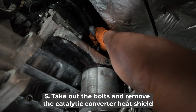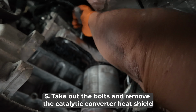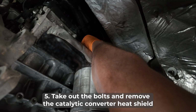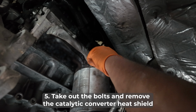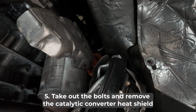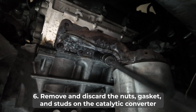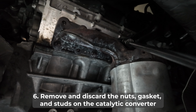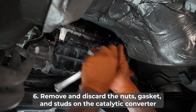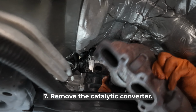Next, take out the bolts and remove the catalytic converter heat shield. Remove and discard the nuts, gaskets, and studs on the catalytic converter. Remove the catalytic converter. Nuts, gaskets, and studs will need to be replaced.